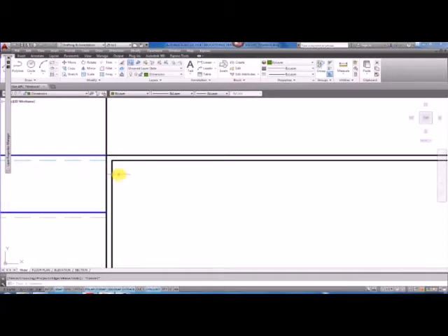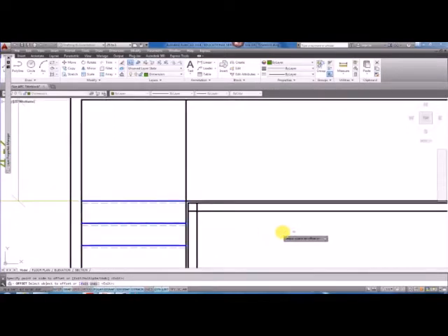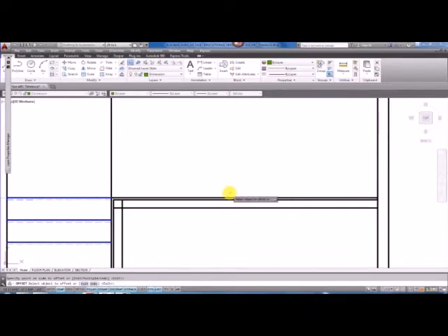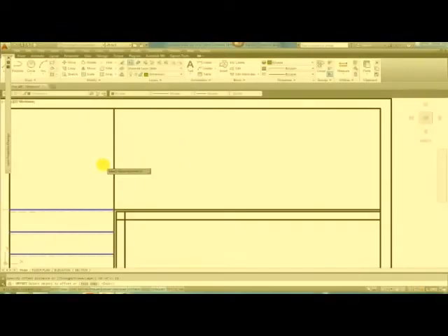And then in this area right here, I'm going to draw the post, and I'm going to move it after I draw it because they're slightly off if we check the drawing. And so that's the first post. And the second post is going to be located at the end of the stairs down this way, which we're going to go and draw our 11" treads by offsetting 11 inches here.